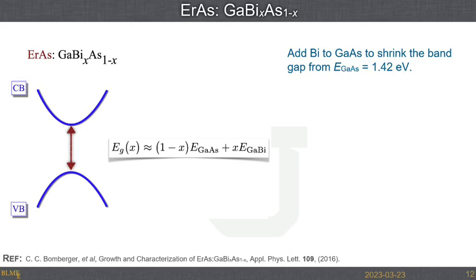When you say a little bit, how much is a little bit? What fraction? By a little bit, how much do you mean? When I said a little bit, which context? Oh, how much bismuth is replacing? About 2 to 3% here. So it's very difficult to go well beyond all of that, just because we know theoretically what gallium bismuth should be, but it's actually not a material that's particularly stable from all of this. So we're only talking a couple % tweaking here.